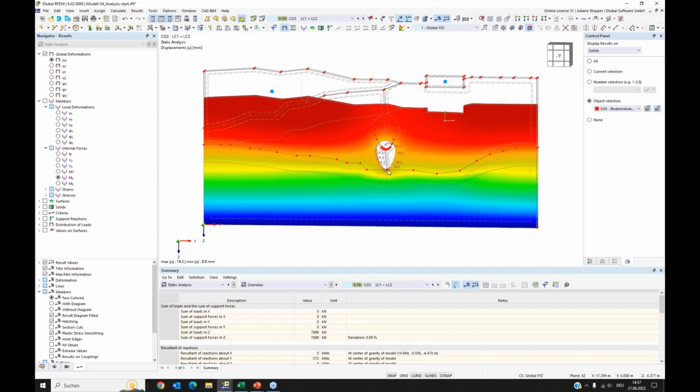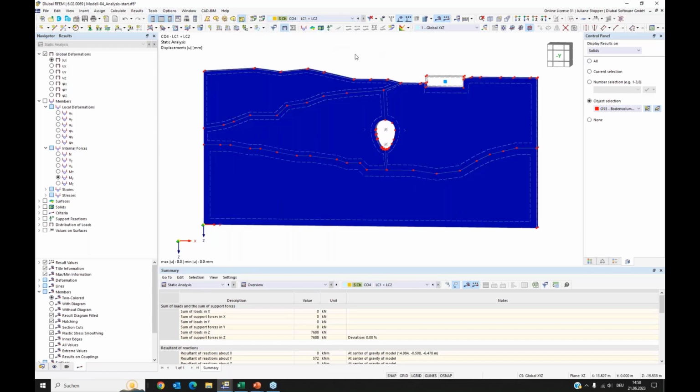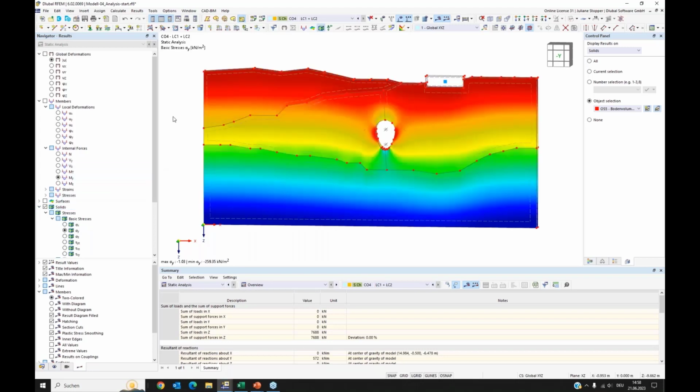That's why we reset it to 0, because when I start my construction of this building, for me there's 0 displacement at the beginning of this load case, or load combination. So that's why we have this copy where we said reset displacement shall be used, and we can see it worked well. The displacements are 0. But if we have a look at the stresses, we will see that we have stresses. And we can also compare it with the previous combination, and we see it's the same.